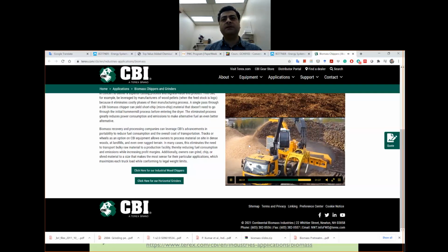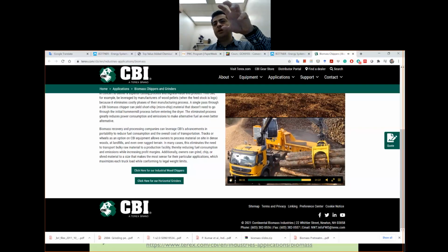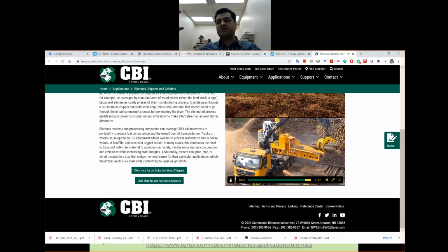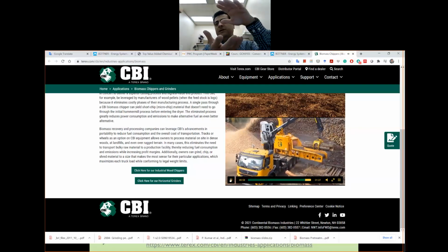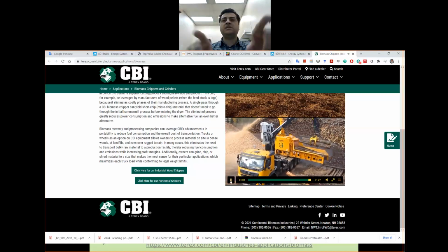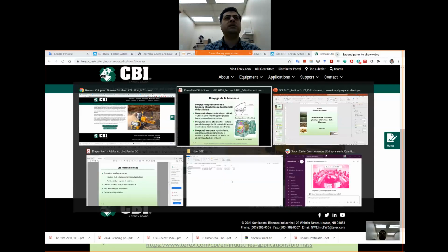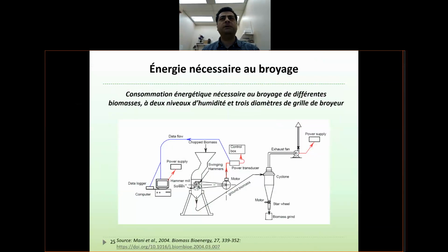But just keep in mind that in a fluidized bed, for example, you have a bed of small particles of biomass. They cannot be large parts. They have to be small parts of biomass, small particles. Then the hot air goes through. Particles are getting mixed together, so you have a good contact between hot air and biomass particles in order to be dried out.